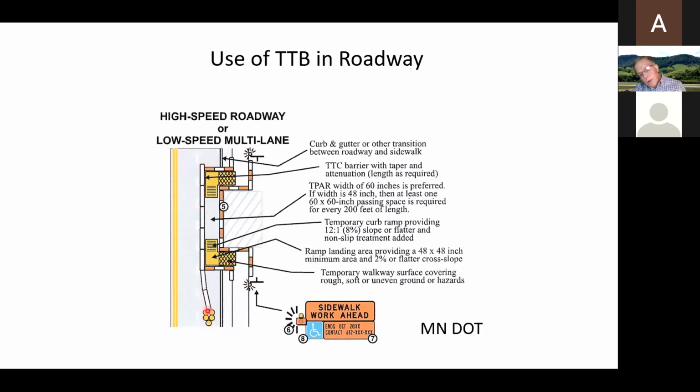In fact, notice we're using impact attenuators at the end here for roadside safety. But on the building side, on the inside of this pathway, we are using channelizers. And of course, we still have the temporary ramps because we're detouring pedestrians into what had been the parking lane.